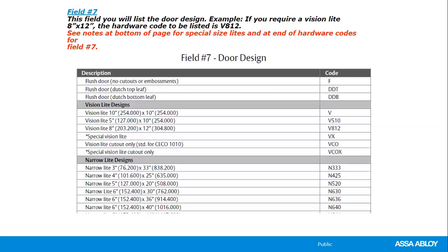Page 15, note number 5 says when special glass size and or louvers are required, prepare a sketch showing cutout sizes, locations, and indicate your sketch number in field 20. So they really want you to put down every single piece of information, and it looks like the LFX is going to be something completely special. The LF is our standard, but they want you to make sure that you know the size and everything else. The LFX is going to be something out of the ordinary.